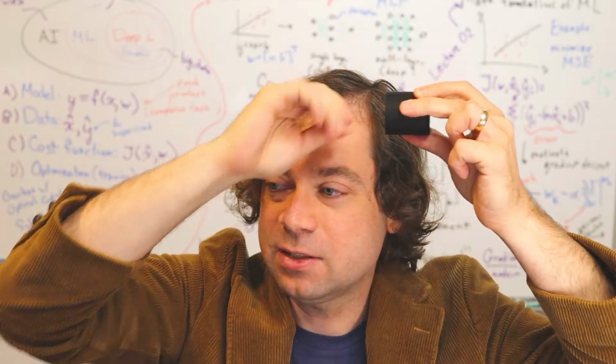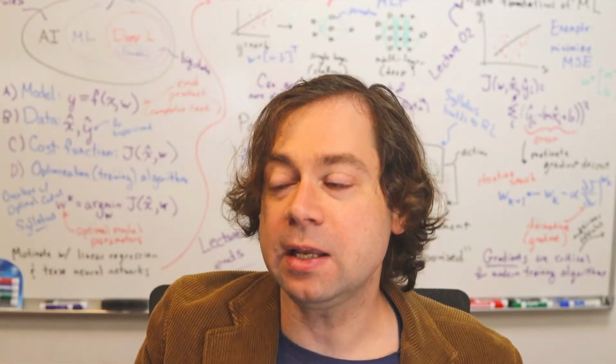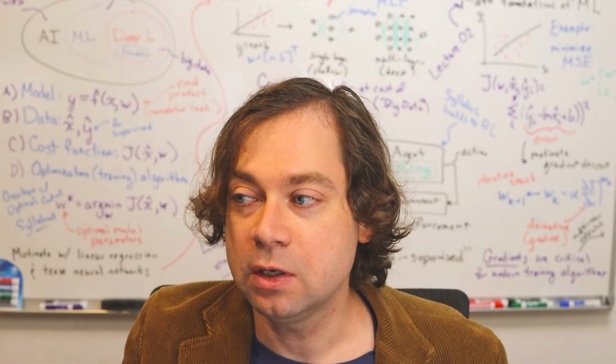The task is because he wants to grab this thing, right? So we will define the task as being the end effector of our arm, and we're going to command accelerations of that end effector in Cartesian space, meaning X and Y. So it goes directly toward that thing, right? And the beauty of it is that we don't need to tune up gains for individual joints.